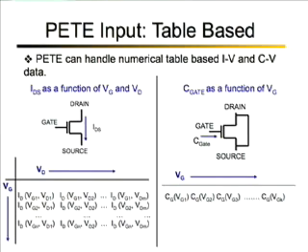And when we say gate input capacitance, we are essentially looking at the MOSFET capacitance, or MOS-C capacitance, which is obtained by shorting the drain and the source, providing a bias to the gate, and measuring the gate input capacitance. Of course, this gate input capacitance will not be a constant. It is a nonlinear capacitor, and it will vary with the gate voltage. So for the capacitance, I have a 1D array where the gate input capacitance varies with the gate voltage, and this is the nonlinear capacitor that we are trying to model.